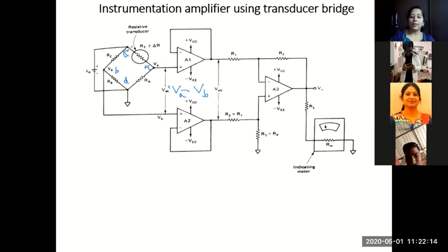The input to the Wheatstone's bridge network is this DC voltage, VDC, which is connected between points C and D. And output is taken between points A and B, and the difference in the voltage measured in between these two points is VAB, VA minus VB. So this is what is measured, as you can see.